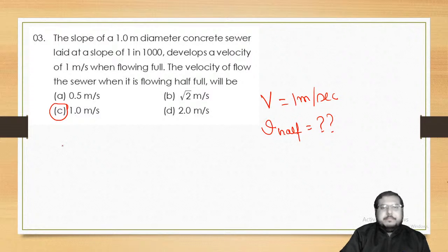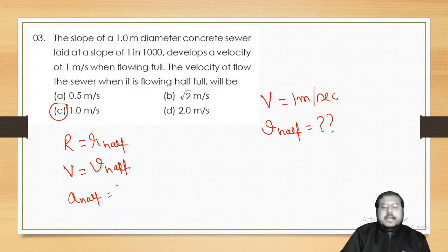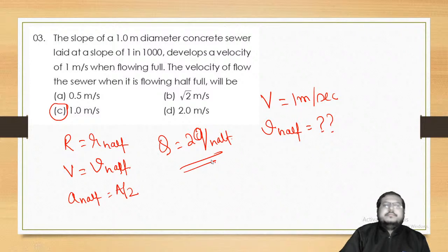Once again, I am repeating the part. The hydraulic radius will be the same. Velocity will be the same. Area will be half of the full flow. And discharge will be half. This fourth thing we need to remember.